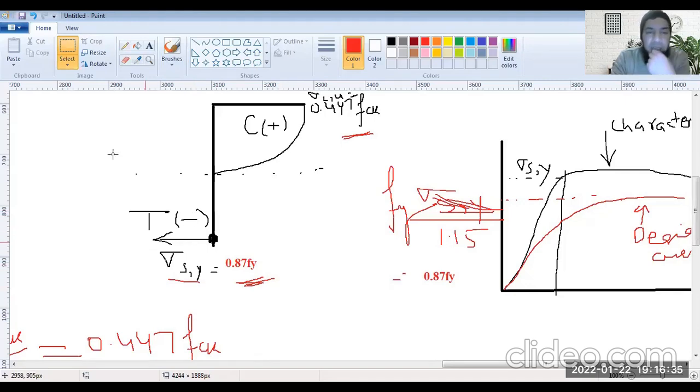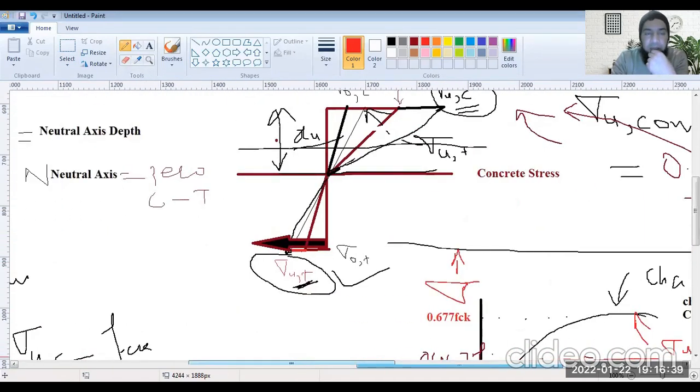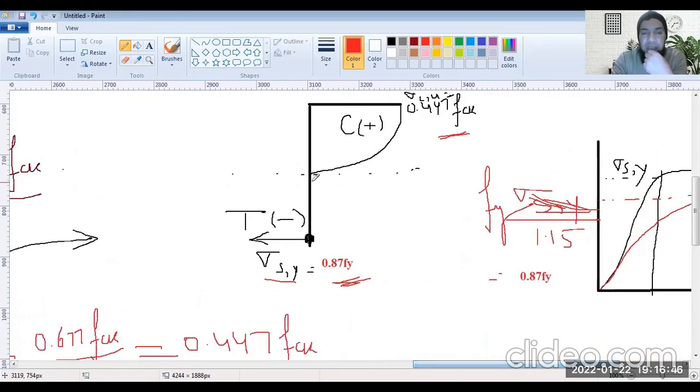So what do we consider? Earlier, when I drew this graph, I showed you there is a tensile stress pattern in the concrete as well. When I put steel in it, I no longer showed you the tensile stress in concrete, because it hardly matters now whether concrete is there or not, because all the load on the tension side is now being taken by steel, and that taken by concrete is negligible as compared to steel.